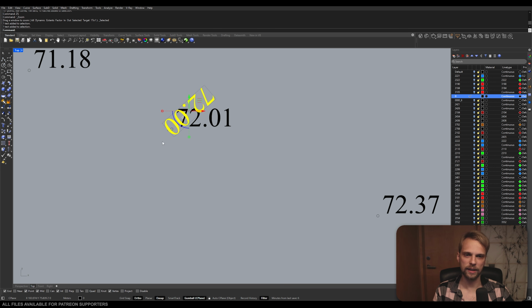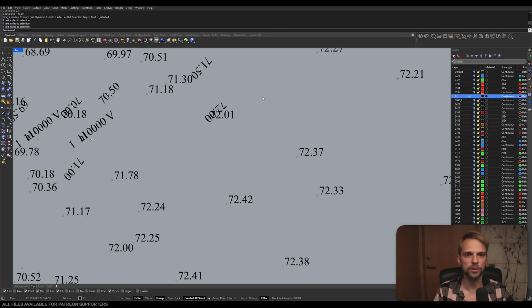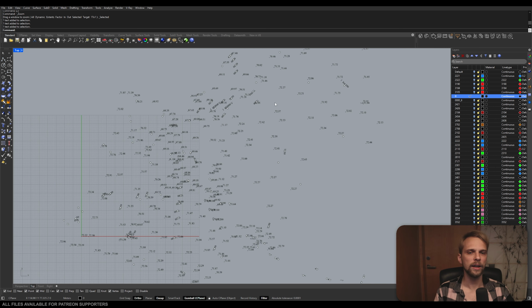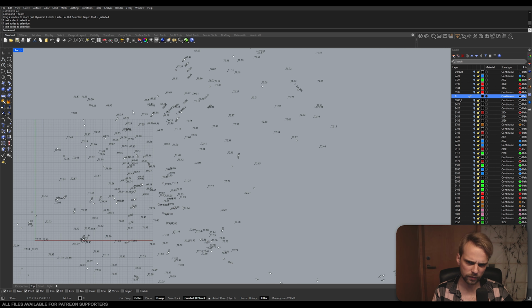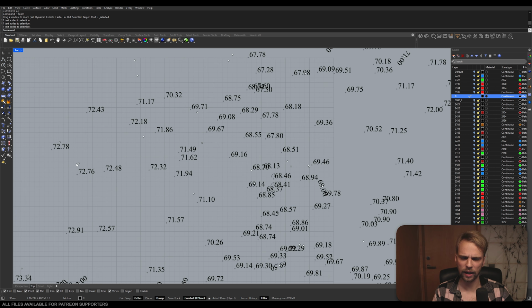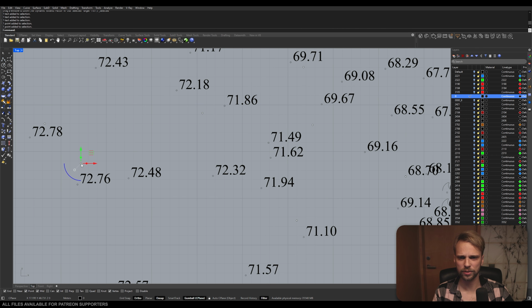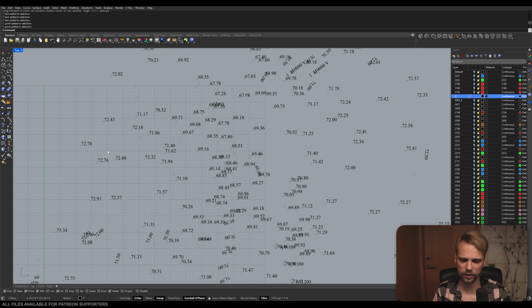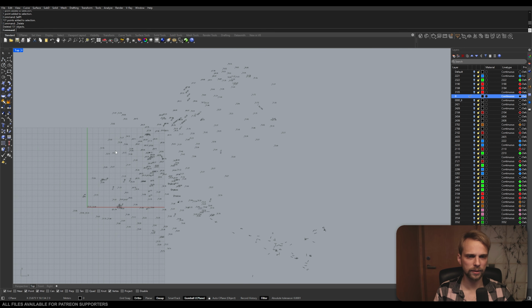Even if the text seems okay, it does not have a point on its own. So this is like an after measurement, a secondary thing that we will also need to remove, right? So there's a lot of stuff that we'll need to do with Grasshopper. With that being said, what we still can do in Rhino is remove all of these unnecessary points. So I'll just type in SelPt, select points, and hit delete, right?